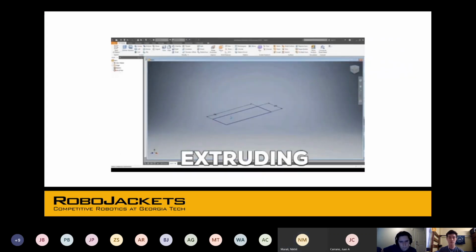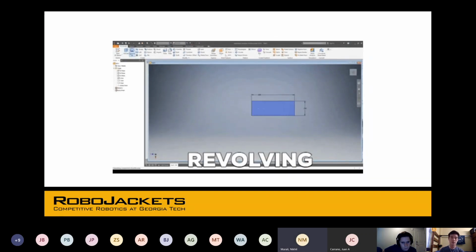So here you can see the person clicked the extrude command in the top left, and then they clicked their sketch. And all that does is shoot it straight up. Then you can define how far you want it to extrude. Same thing with revolve. You just click the revolve command, click your sketch, and also click the axis that you want to revolve around, and it will all revolve.